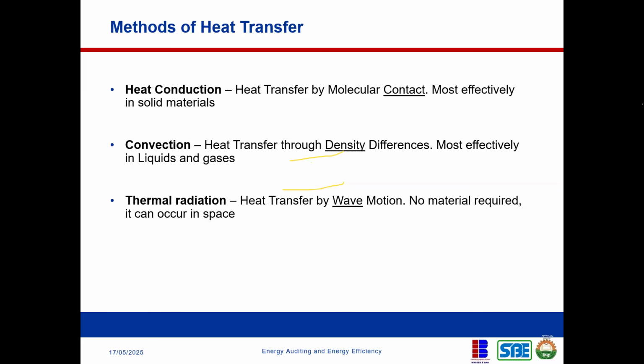So the water from the bottom gets heated, it moves, it becomes lighter. Okay, so it's a density difference. Once something becomes hot, it becomes lighter. So it moves to the top, and the water that is cold, or that is at a lesser temperature, is heavier. It will now move down. So that density difference is what actually makes the water heat. I mean, the entire water in your kettle begins to heat. At a point, it gets to a boiling point and it begins to boil. Now, that is convection. Let's talk about radiation.